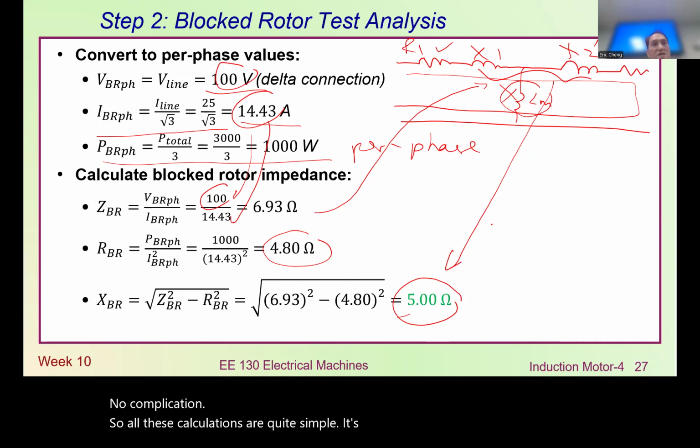Then, because of the winding, when you always operate at the upper limit, the aging problem arises and the insulation may eventually break down. So you call it latent damage. They may have more chance to break down. We don't like the motor to break down. Most motor breakdowns are usually in the winding. Usually a motor can last some 10 years, 20 years without too much problem. When we see a motor breakdown, it is almost always the winding.